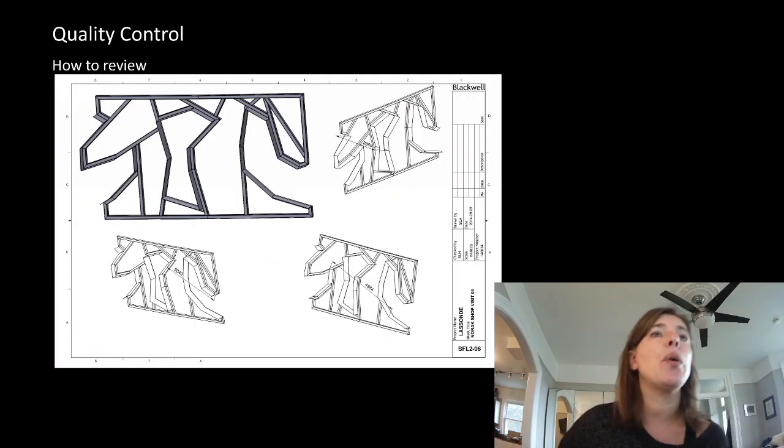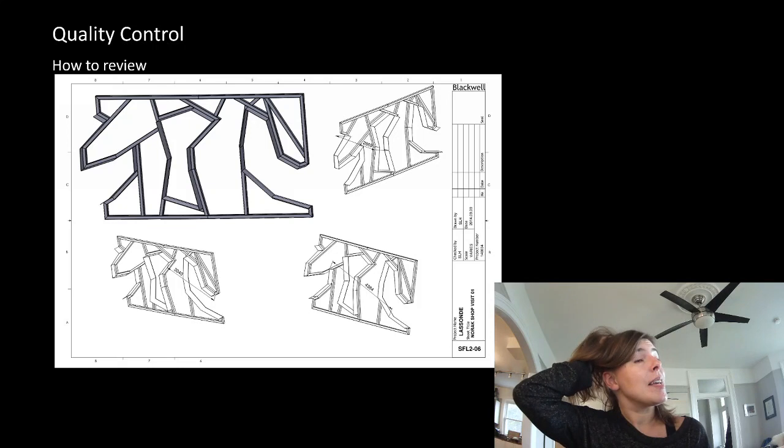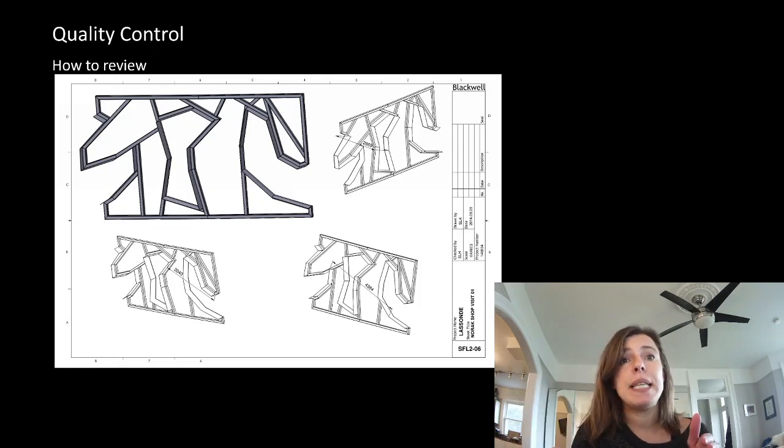So how do we review it? Well, it's impossible to say this should be the dimension, because how do you guarantee that? You have no context to it. In X, Y, and Z, in a 2D plane, you can assume everything's at a right angle and your measurement should be right. As soon as you get skewed angles, you need multiple measurements.